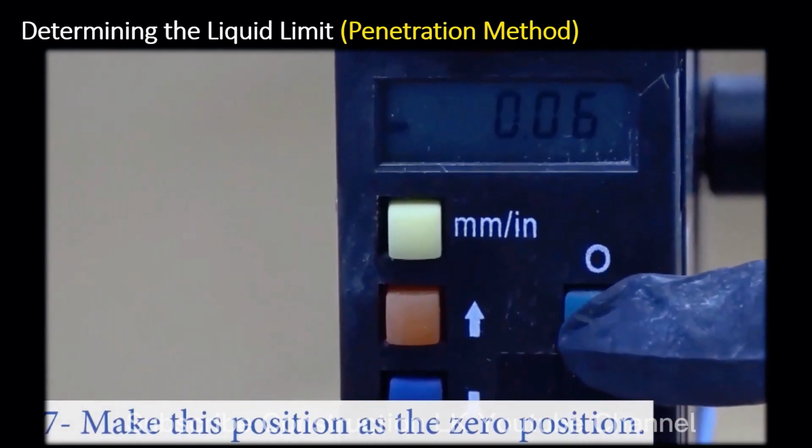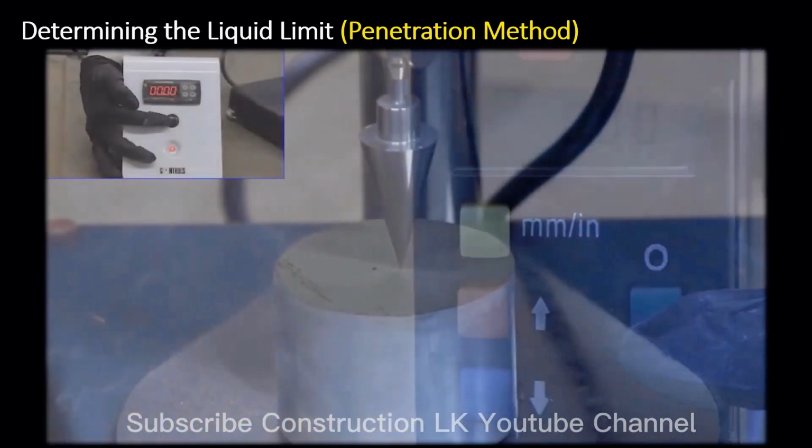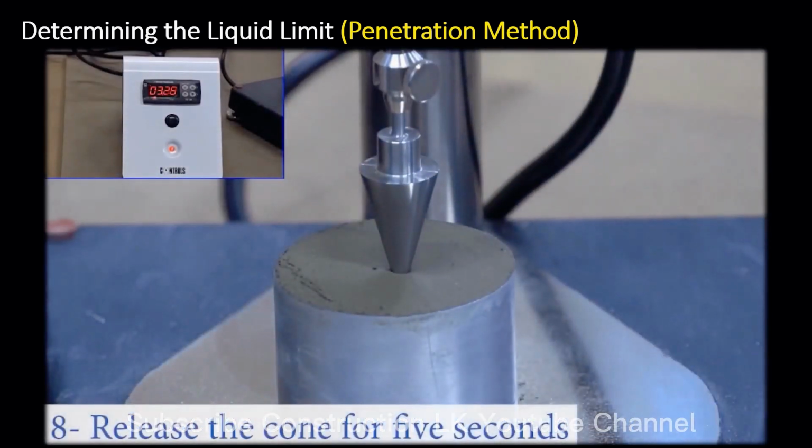Now set the displacement reading to 0. Then release the cone for a period of 5 seconds and its depth of penetration into the soil is measured.